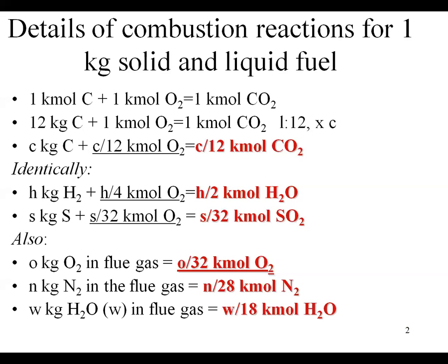So when we are running a calculation of the combustion process, it is important to know how much fuel I need in order to produce so much heat energy. This is the first step. Secondly, how much air I need, so how much oxygen I need to run the combustion of the fuel needed in order to have as a result the needed heat energy. But oxygen is not available in a molecular form alone. It is very available in the air, but it comes with nitrogen. The composition of air is well known.